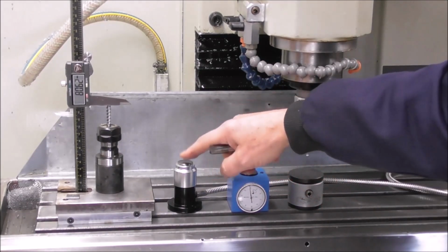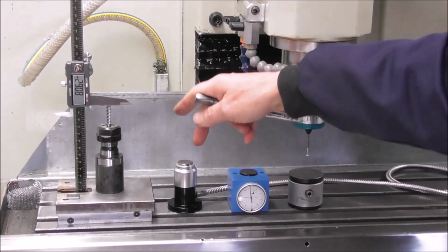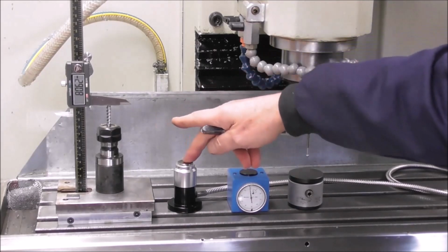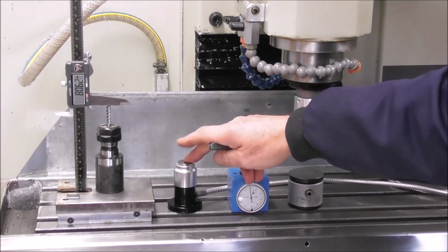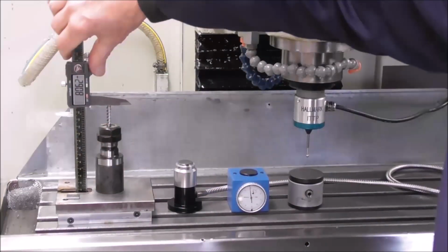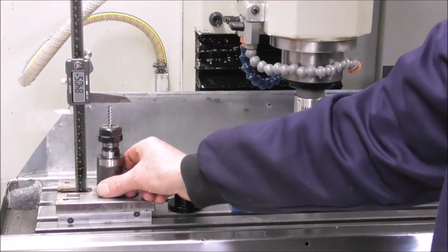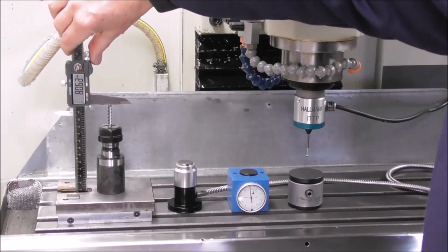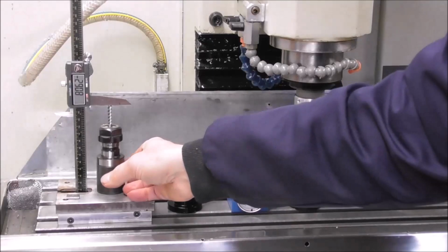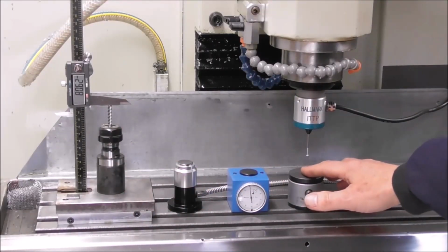Or you can have an automatic electronic tool setter, and PathPilot and probably Mach 3 have a probing routine that brings the tool down onto the top of that electronic tool setter and loads the tool height automatically into the software. Or you can measure your tools off the machine with various devices such as this digital height gauge, and you do a manual measurement and load it into the software. So that's a quick overview of 4 different types.